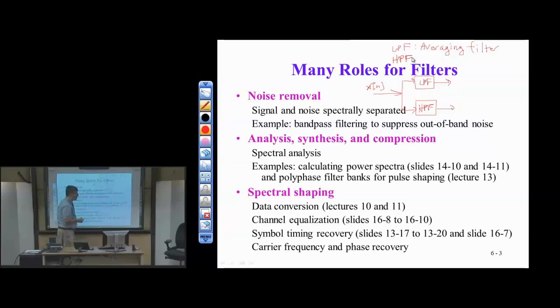It turns out we can do something very simple here to combine x0 of n and x1 of n back to one signal that has all frequencies in it. What we can really do here is just simply add the 2 results to get back to a delayed version, really, of x of n. Or we could even subtract the 2 results, and that also works pretty well. Okay, so let's look at what that has.